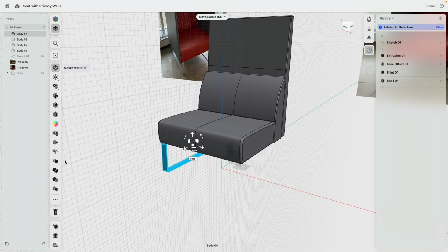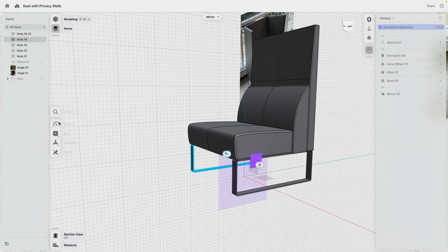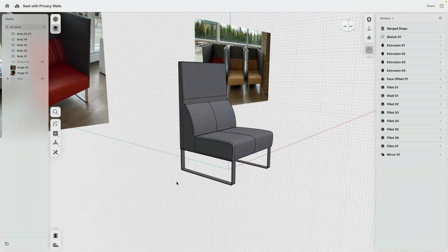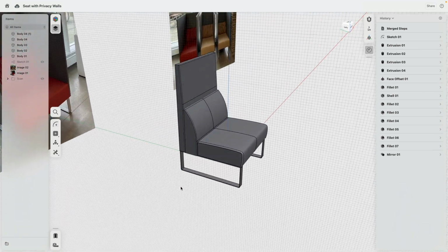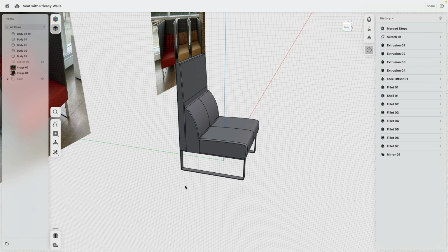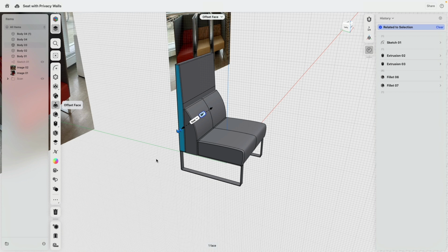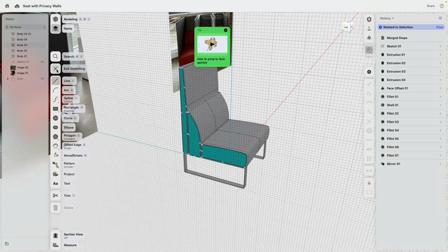Here we can double click, select the object, and then we mirror it over the origin. And so how do we do the other profile now? There are various different ways. I will simply select one face here. It doesn't matter which one you select. You can go with this one. And then we create a sketch on that face.